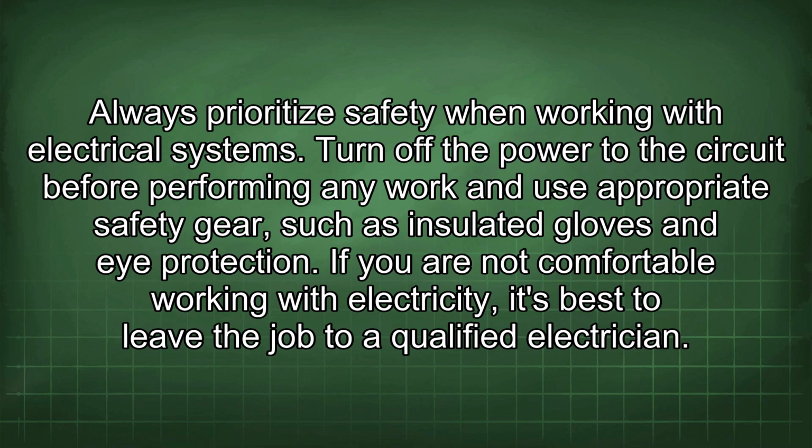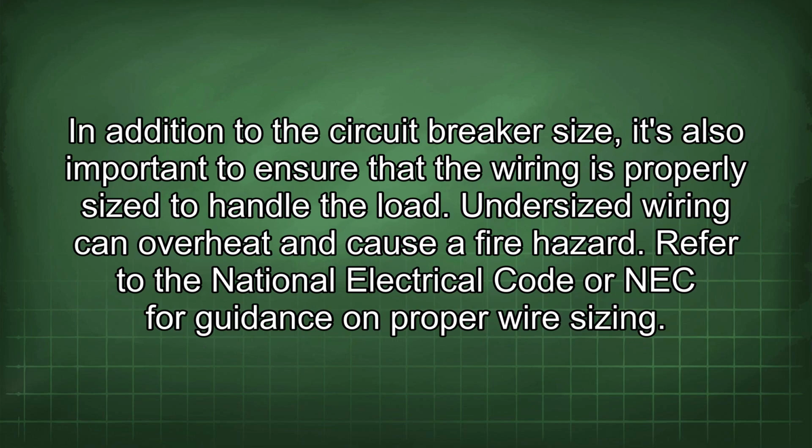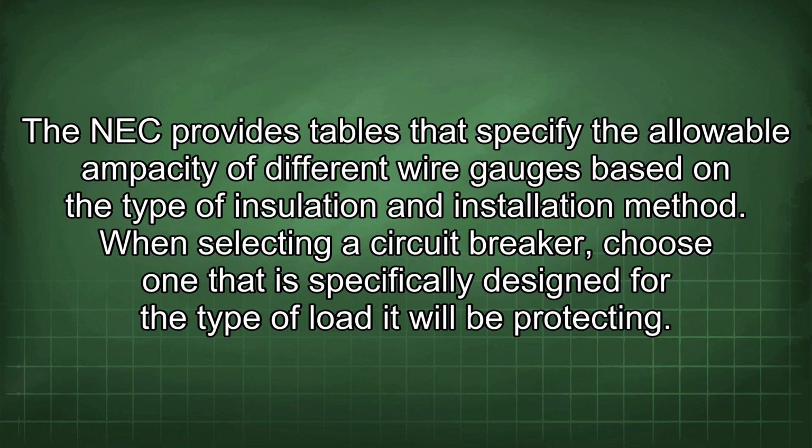qualified electrician. In addition to the circuit breaker size, it's also important to ensure that the wiring is properly sized to handle the load. Undersized wiring can overheat and cause a fire hazard. Refer to the National Electrical Code, or NEC, for guidance on proper wire sizing. The NEC provides tables that specify the allowable ampacity of different wire gauges based on the type of insulation and